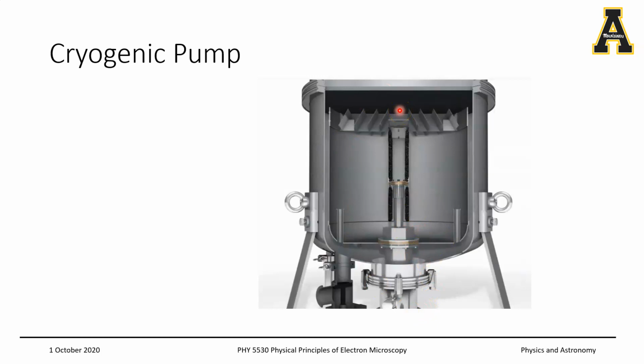Usually you can keep the system cold for hundreds of hours before a regen is necessary, but if you end up getting poor vacuum, most likely it's because your charcoal filters that contain the trapped gas molecules are close to saturation. So you shut down the system and you begin the regen process, which is essentially just heating it up and connecting it to a roughing pump, which sucks away all the gas molecules that were trapped within the surface of your cryo pump.